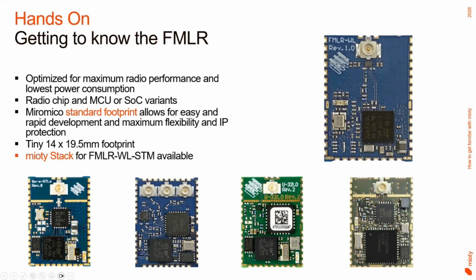STM32WLE chipset that, as Mario already mentioned, has mioty stack support from Stackforce. However, since we have a standard footprint, it will also be really easy to change later, for example, to a Texas Instruments, a Silicon Labs, or an STMicroelectronics chipset that has bidirectional support as well, without having to redesign your carrier board.